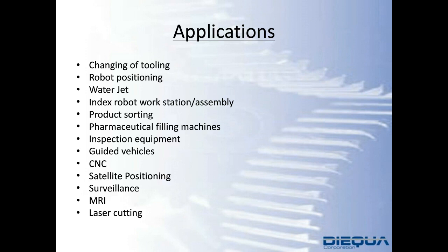Water jet applications could be bundled together with laser cutting, for example, or inspection arm, right, or assembly arm. These are applications that would greatly benefit from a hollow bore on the robot flange. This way you're allowed to run the plumbing through, the electrical, the various network cables for communication, to run signal, to gain feedback if you have sensors.